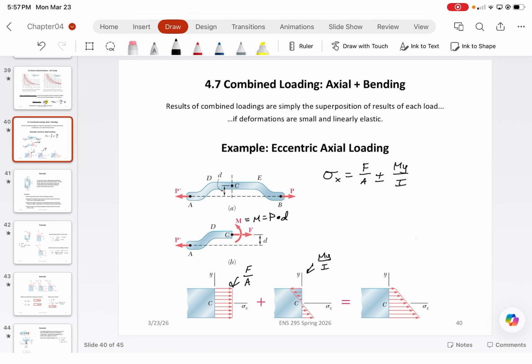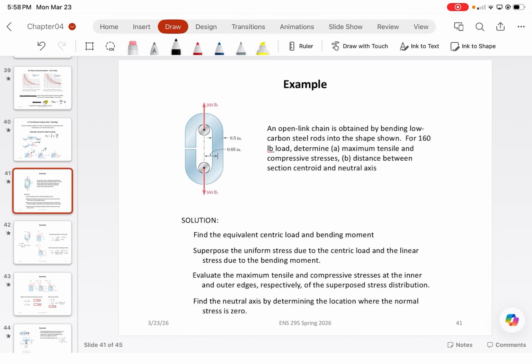It's like pulling on a rope and saying that the rope is undergoing both tension and compression. It's either tension or compression. Only if it was bending would it undergo both, and that would mean that the load is positionally dependent. Make sense? Awesome.